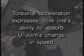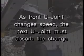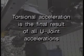Torsional acceleration expresses the driveline's ability to absorb each U-joint's change in speed. U-joint phasing and angularity is critical to torsional acceleration. As the front U-joint changes speed, the next U-joint must be phased to absorb the change. Then, the next U-joint must absorb that U-joint's changes, and so on. Torsional acceleration is the final result of all U-joint accelerations as they add up or cancel each other.